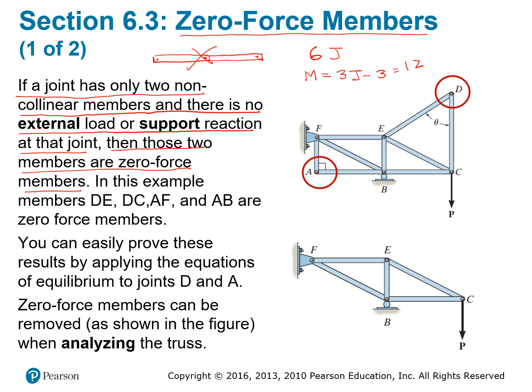We consider 2 members that connect at a certain angle, and in this case, A is one of the examples. And it's not only about how these 2 members are connected, it also has another condition: no external load. If you look at A, there's no external load, right?